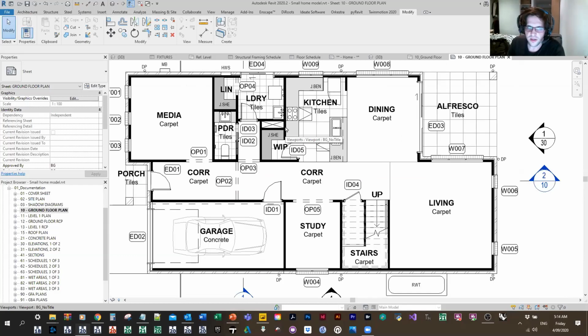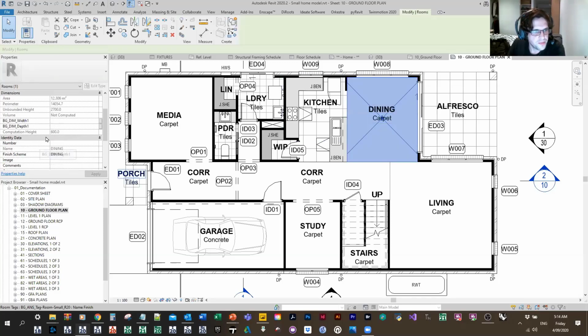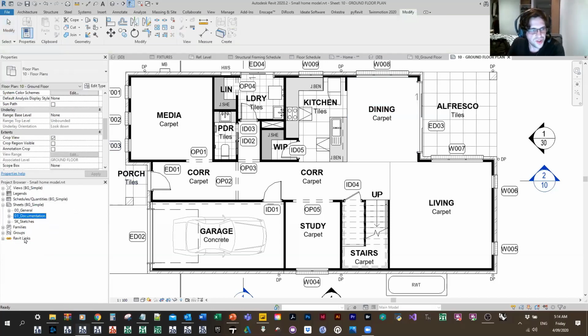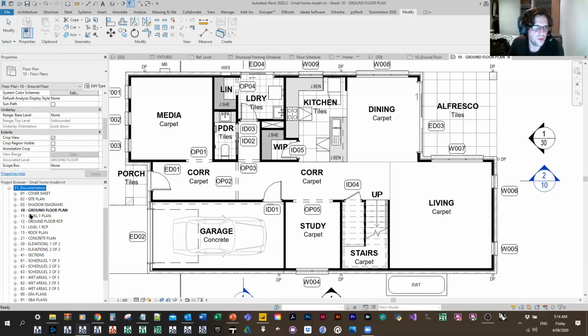By default, because it's a really small scale project, I do a few little Revit hacks, like I paint the concrete with carpet just to not have to model all the carpet in the project, but in Enscape I can still see carpet. What I do instead is embed a field inside the finish. In this case, I have a finish scheme, which is tied to a key schedule, which will be part of my Revit hack that I talk about later, because I think this is a really handy technique. It's essentially telling the room what its floor finish is. And then instead of scheduling the floors, I just schedule the rooms.